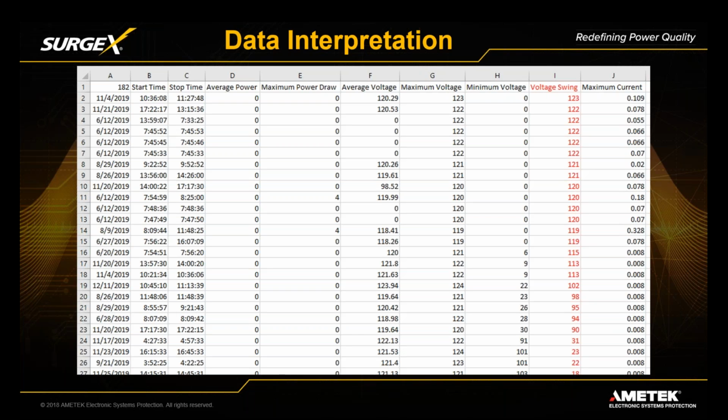And the reason we're looking at this is, what does that mean? If your voltage tends to be pretty stable, your average, your max, and min are all roughly close to the same value, that means your supply is adequate for the load, and nothing weird appears to be going on. If your voltage frequently is low, like your minimum voltage is below some threshold, there are guidelines out there from utilities and the NEC, then that could mean various things. And if your voltage is regularly higher than some other threshold, that could mean something different. And if you notice a wide swing between your maximum and minimum measured values in a given 30-minute window, that's a strong indicator of something else also. So that's why these measurements are really valuable.